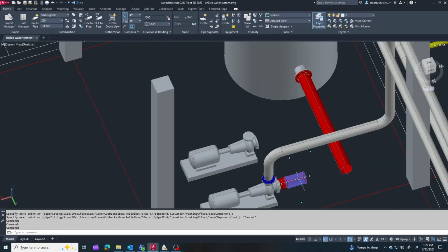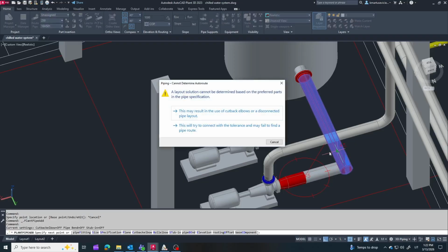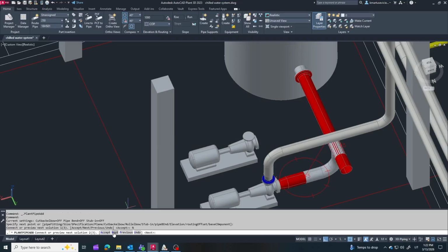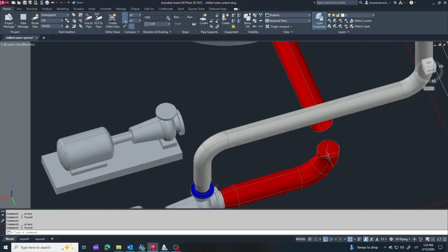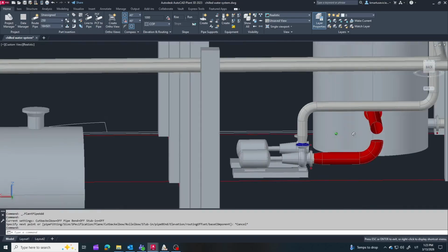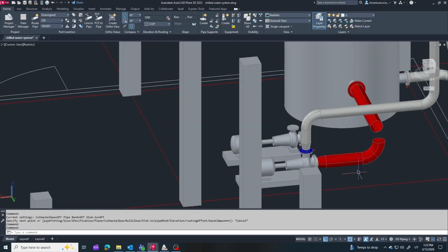Another benefit of the buffer tank is system stability. Without enough water volume, chillers may start and stop too frequently, which reduces efficiency and increases wear. The buffer tank adds thermal mass, allowing the system to operate more smoothly.